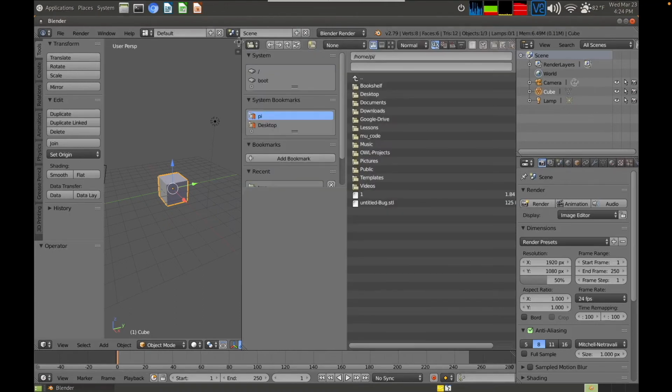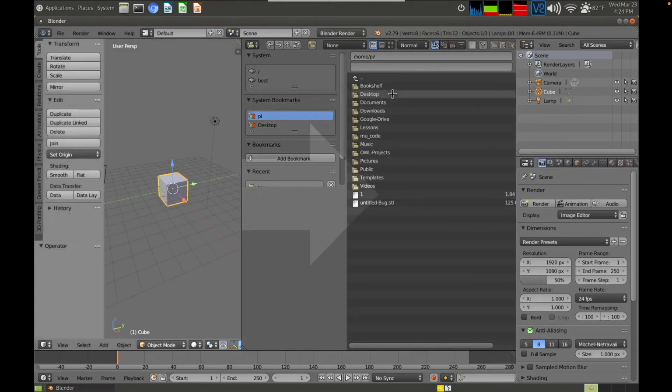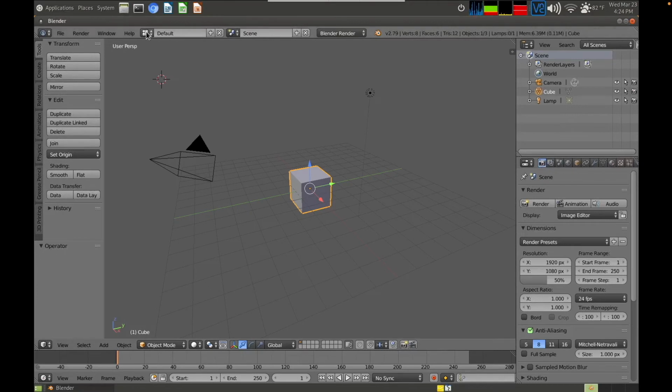The way that you can combine an editor is by dragging in the same area where you can create editors, and then moving over. You see the giant arrow? That collapses the area. So even though the workspaces come with a default area setup, you can change any of the workspaces. And also in this drop-down menu, you could create more workspaces. So there's a plus sign right here, and also an X sign to delete workspaces.